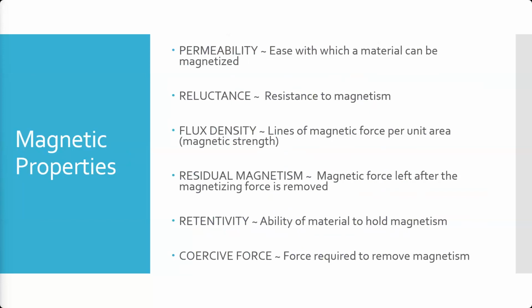So if you have something with a high retentivity, something that will stay magnetized, and you want to demagnetize it, like if you want to demagnetize your part before you put it back in the airplane, how much coercive force do you need in order to do so? Okay.